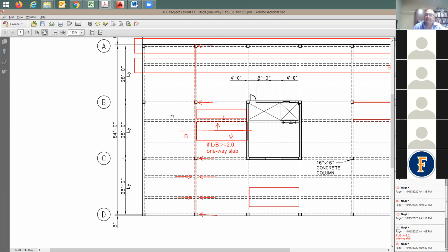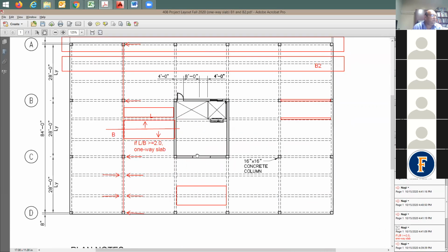How about the slab itself? How can you design the slab itself? What do you mean? When you cut a section through here and look at the slab itself, aren't you going to put reinforcing in the slab? I'm going to say yes. How do you put reinforcing? Well, reinforcing is going to be running across. So to design the slab, I'm going to be taking here a strip.